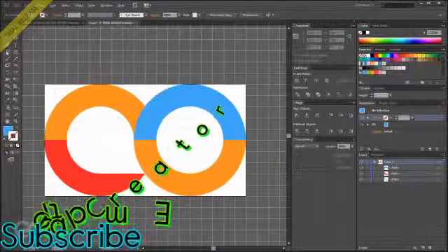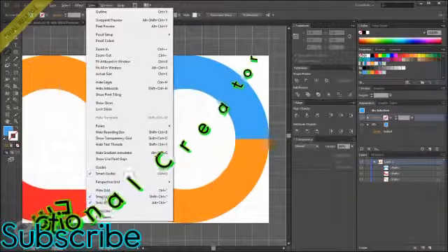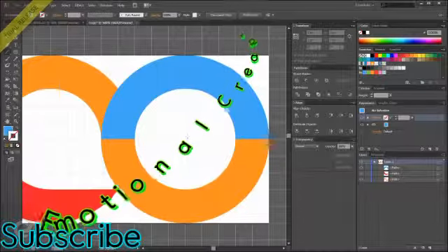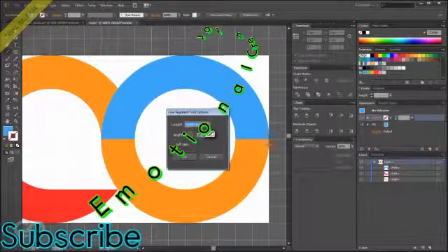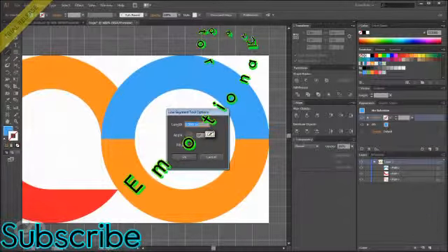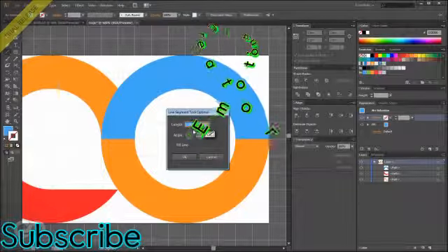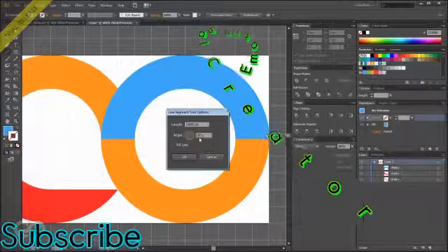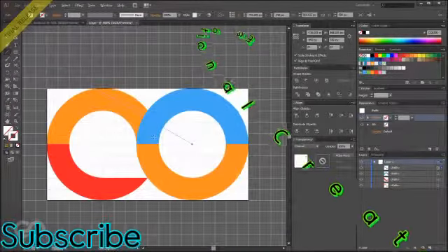I'll go ahead, take the line tool, and because I have my grid snapping already turned on, I can come back here and click here exactly in the center. And now I have my option to create a line of any length at any angle. I'll just set this length at 1000. I don't really care about the actual length, and here the angle is supposed to be 150, and I'll create that. So as you can see, the line is created.